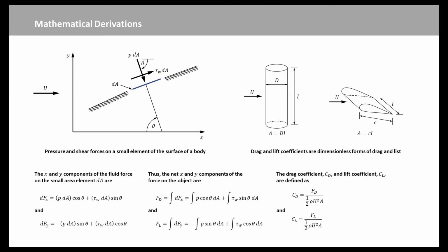Considerable effort has gone into determining these quantities, but because of the various complexities involved, such information is available only for certain simple situations. Without detailed information concerning the shear stress and pressure distributions on a body, the two equations cannot be used. The widely used alternative is to define dimensionless lift and drag coefficients and determine their approximate values by means of either a simplified analysis, some numerical technique, or an appropriate experiment.